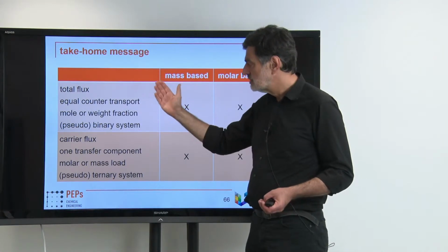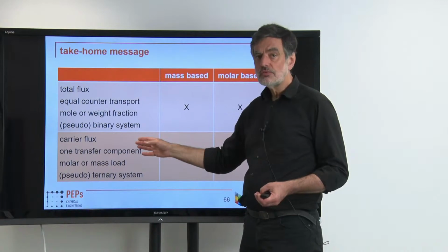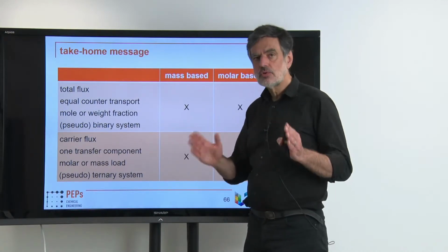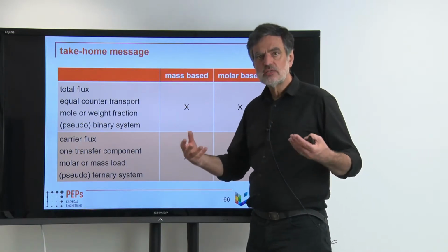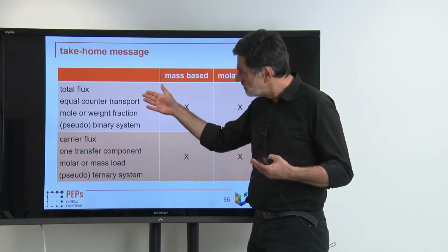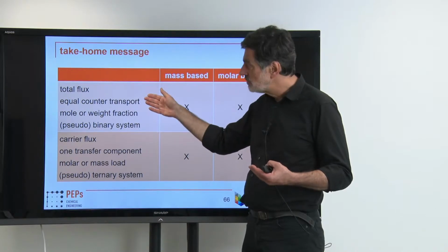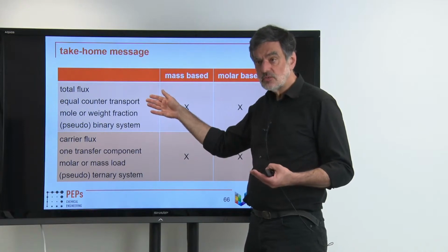It's the famous case, whereas the other option that we have mostly applies to solvent extraction or absorption. Because there we have carrier flow rates, we have a liquid and a gas stream. They are generated not by evaporation, whereas in rectification the vapor is produced by evaporating the liquid, and the liquid is produced by condensing the vapor.